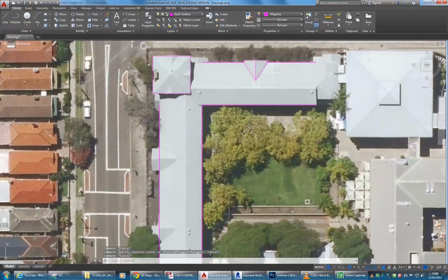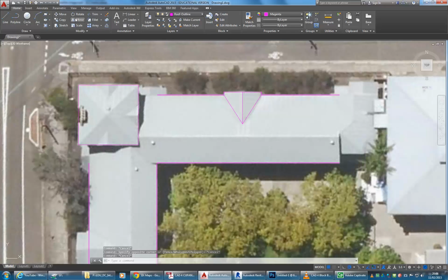So do you remember with the editing tools how to select things when you use commands like copy and move, rotate? It's up to you if you want to select the objects first, or start the command first. So I'll just show you both ways maybe to remind you. If you select the things first, like I've just done, then click copy, you can then pick them up and move them over. Or you can click on the command first, select the objects, and then you just need to remember to press enter to let it know you've finished selecting, which you wouldn't do if you'd selected the objects first.